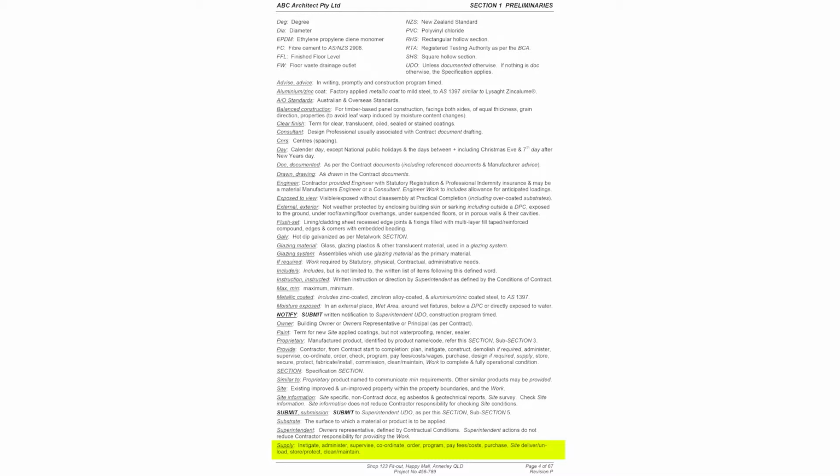All big and small detail needs to be unambiguous to avoid dispute. Simplicity is also vital. For example, site subsection specifies dilapidation records. For these records, some specifications have all parties burdened by sign-off on a joint pre-construction inspection. This is a huge task and needs simplifying. This clause states the contractor makes a record and any damage complaint is their responsibility if the records can't show otherwise. If we seem to skip around in this video, remember this is simply an overview of main points.